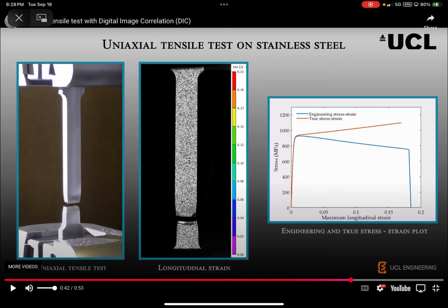But you guys see, for the true stress strain curve, the math is showing it's going to continually keep increasing, right? But in actuality, because you've got the reduction in the cross-sectional area, your stress is actually being reduced because it can't carry as much force now. So it's compensating by deforming more. And obviously it just goes straight down to zero once it fractures, because at that point it's not carrying any load. Make sense? Are there any questions about this at all?